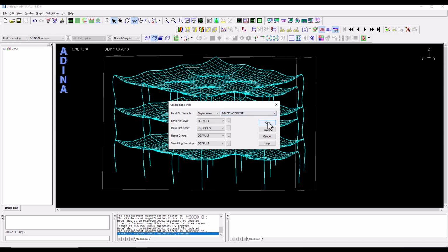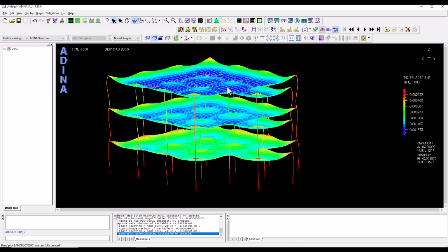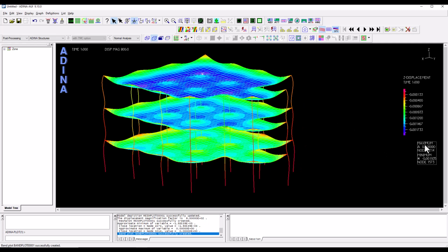So if we look at the Z displacements, for instance, under self-weight, we have something in the range of just under 2 millimeters, which is reasonable. If we had made a mistake with some of the units, or the Young's modulus was out by a factor of 1,000, or for instance a cross-section or the pressure that we have applied, we could see that it is clearly a few orders of magnitude out or wrong.